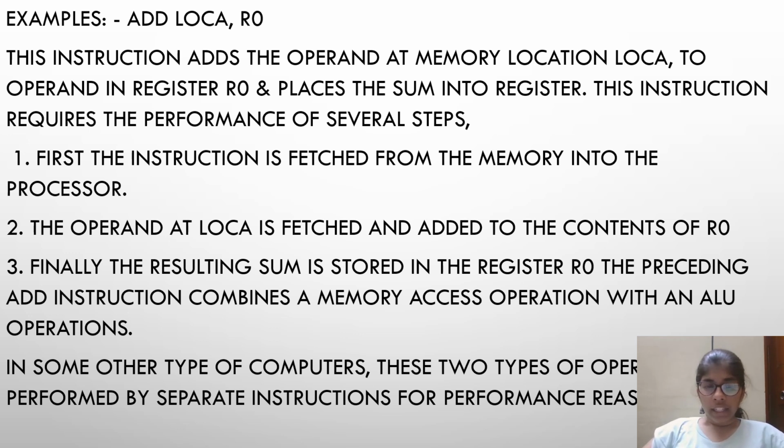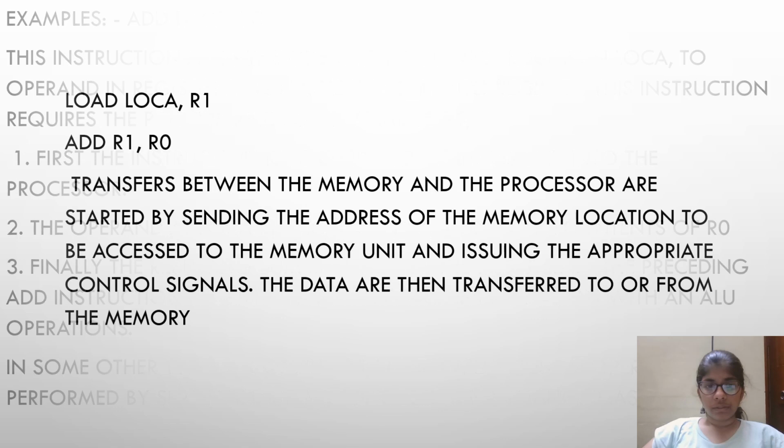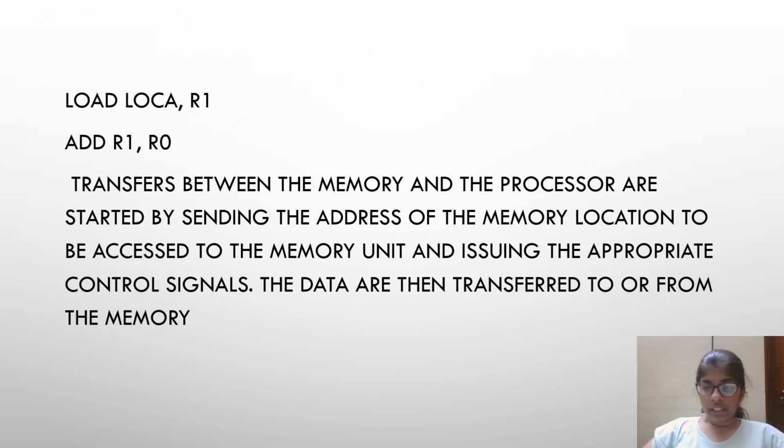The preceding Add instruction combines a memory access operation with an ALU operation. In some other types of computers, these two types of operations are performed by separate instructions for performance reasons. For example, Load LOCA, R1, then Add R1, R0.